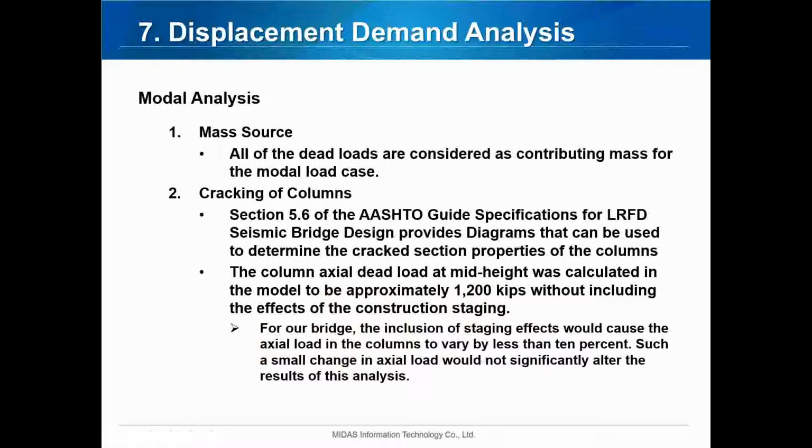So moving on to the displacement demand analysis. Here I wanted to basically talk about two items. That is the mass source, and so all of the dead loads were considered as contributing mass to our model. And then the other item is the cracking of the columns, like we mentioned.